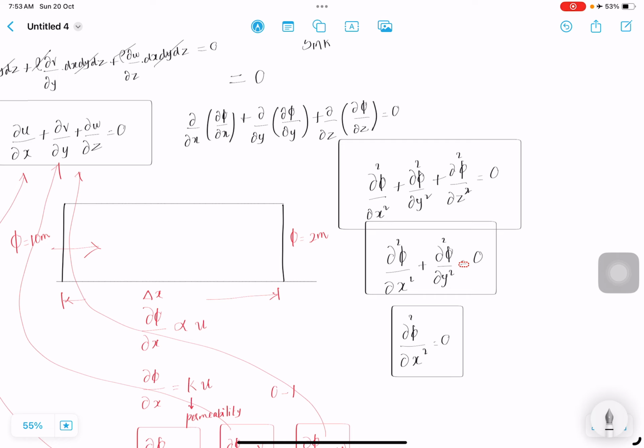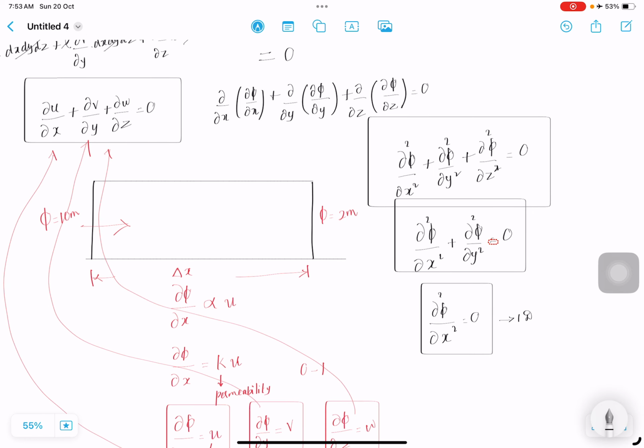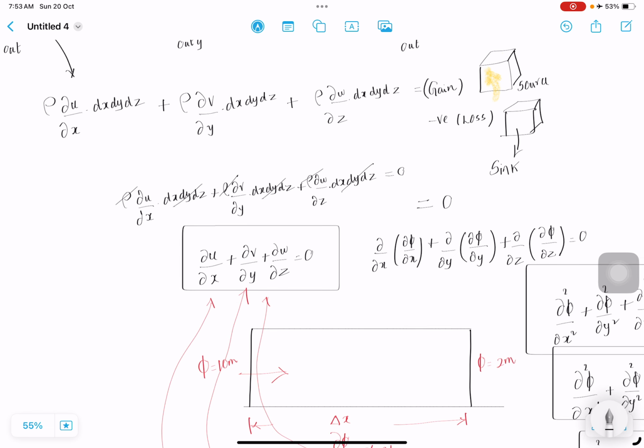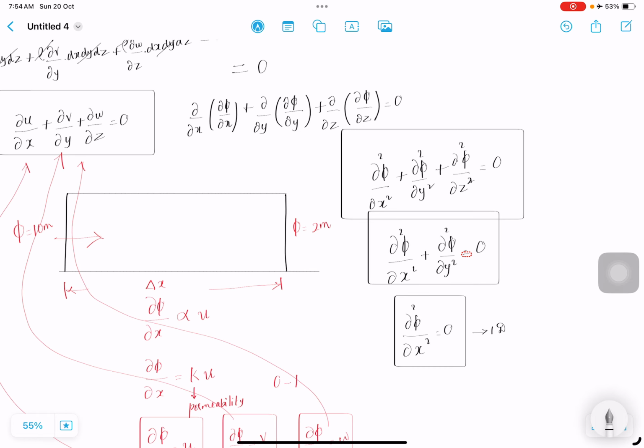But when we do the finite element formulation, in the next part, we are going to derive the finite element formulation for 1D fluid flow. So I'm going to modify this 1D equation slightly. I'm just going to add some details to this equation because we have ignored certain terms. For example, when we multiplied and divided by the volume on the left side, we took this dx, dy, dz on the right side, so this volume just vanishes, right? We are not going to do that for 1D. We need it for finite element formulation. So we will keep the volume.